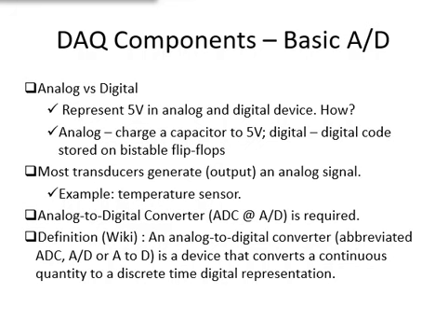For example, a temperature transducer might generate an output voltage that is proportional to the sensed temperature. If the temperature were to vary in a continuous manner, the transducer output will show continuous variations. There are possibly an infinite number of possible output values. The analog to digital converter is the device required in a data acquisition system to convert the analog transducer signal into the digital code used by the computer.